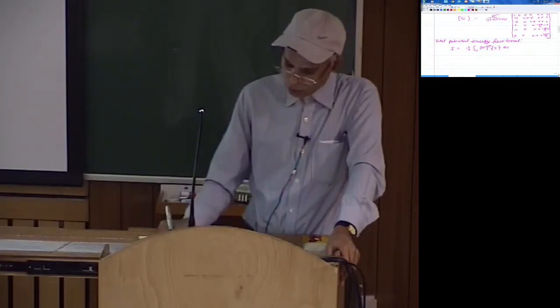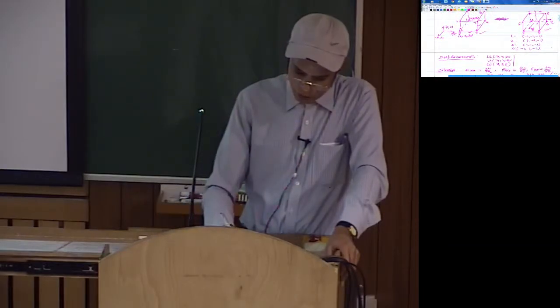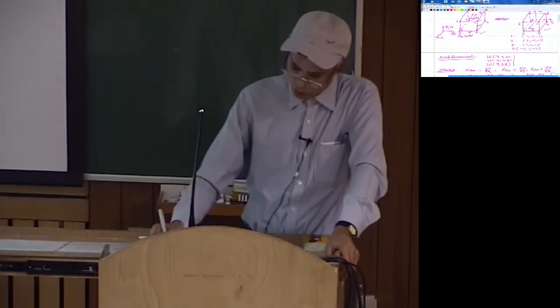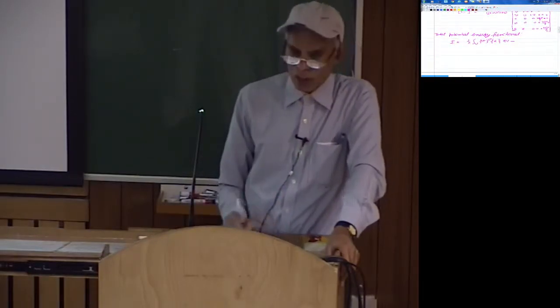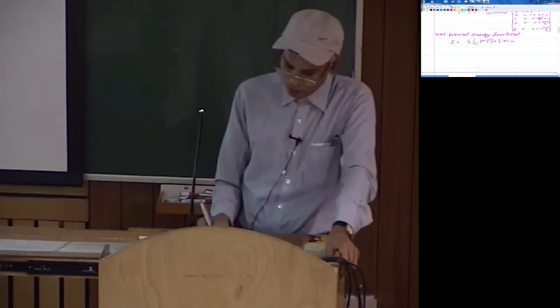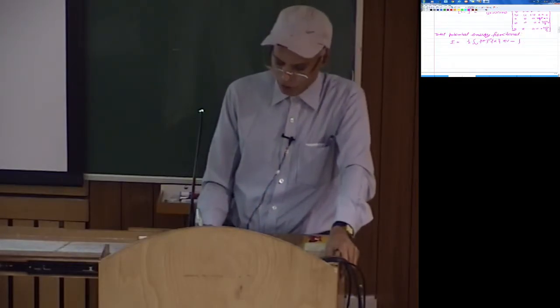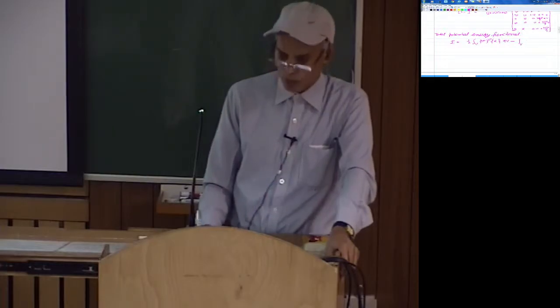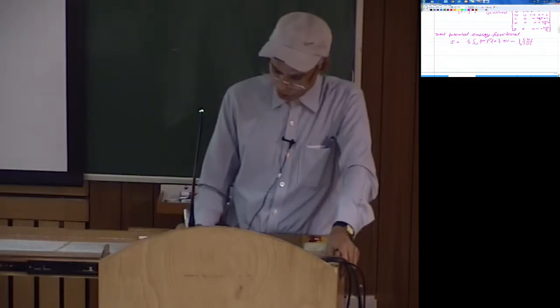And then you will have, let us say, body forces within this element having components along x, y and z directions. So the potential of those forces, again with respect to datum as the undeformed configuration, you get the body force contribution as integration again over volume, and then let us say the body forces are Fbx, Fby and Fbz along the x, y and z direction.